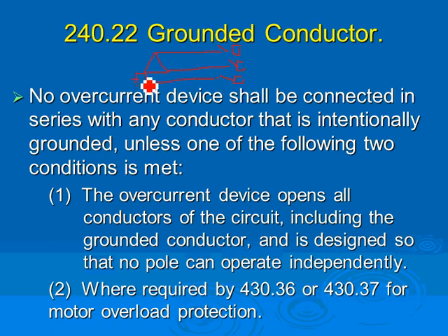Now, even though, remember, this is grounded here, the only exception for this is if I'm feeding this to a motor, and this fuse has a dual function. Function number one is an overcurrent protection device, which means short circuit and overload at the same time. So if you decided to use the fuse as overload and short circuit protection at the same time, which is allowed by code, not a good idea on a bigger system. Anybody knows why not a good idea?